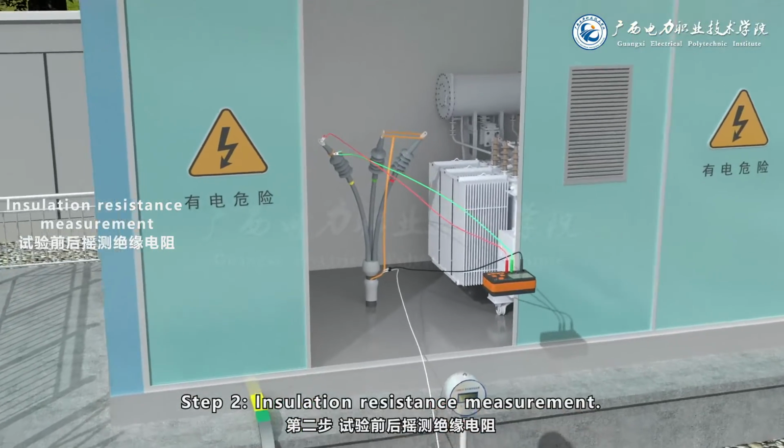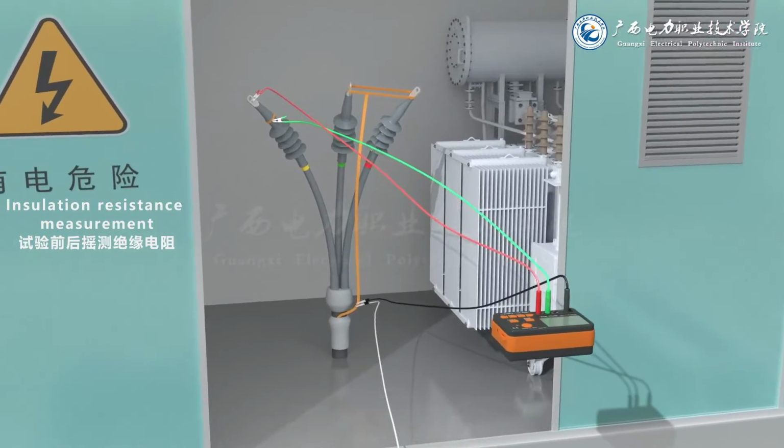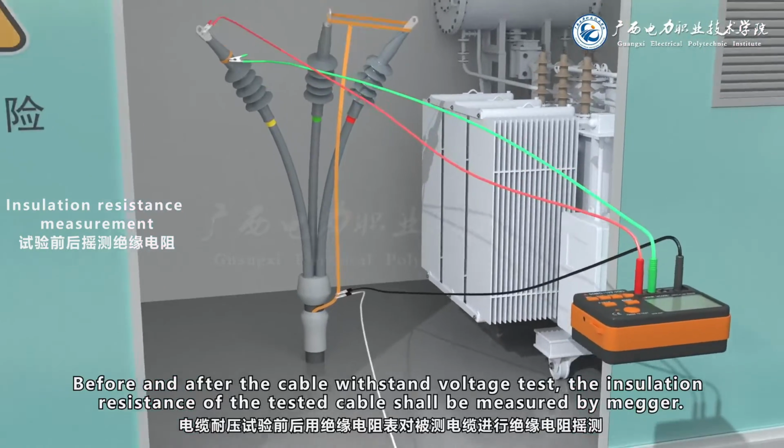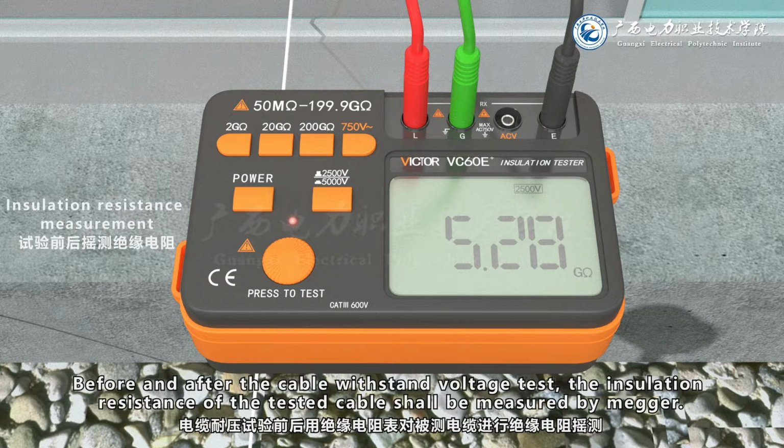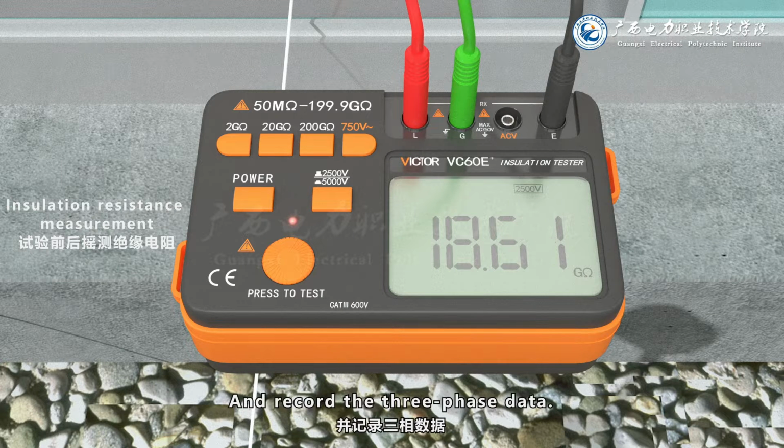Step 2. Insulation resistance measurement. Before and after the cable withstand voltage test, the insulation resistance of the tested cable shall be measured by Megger and record the three-phase data.